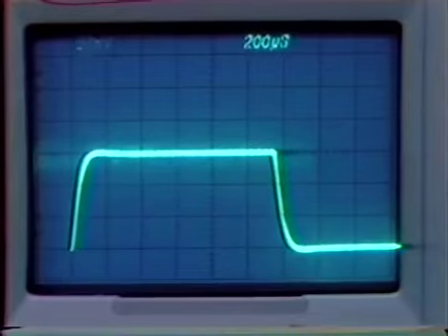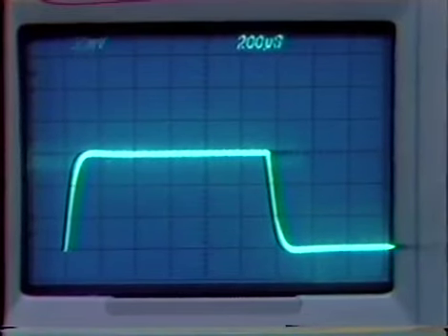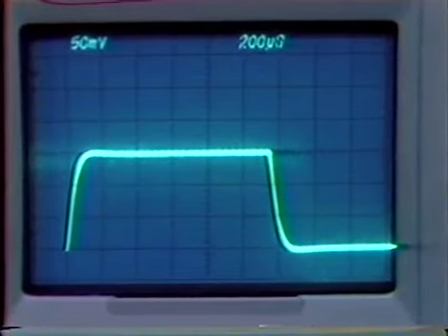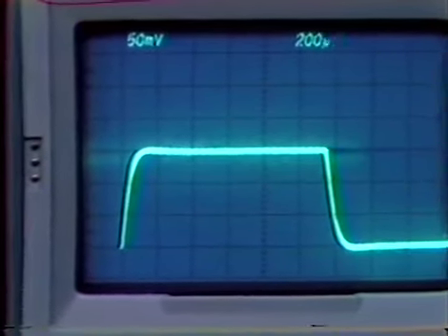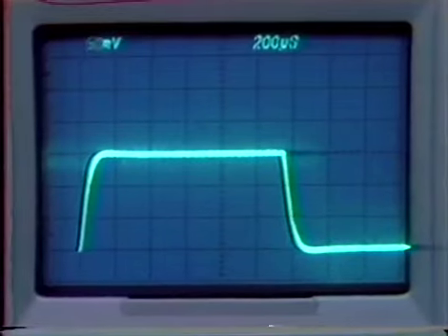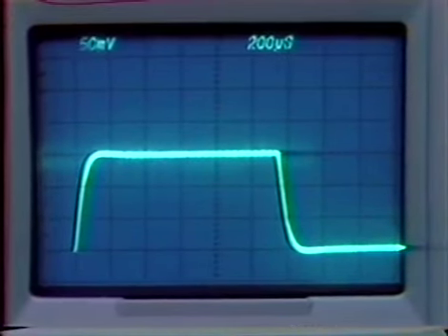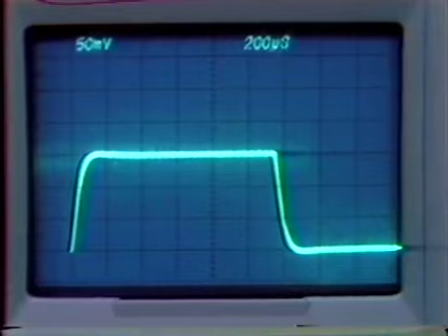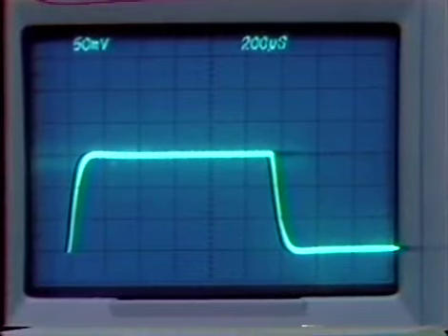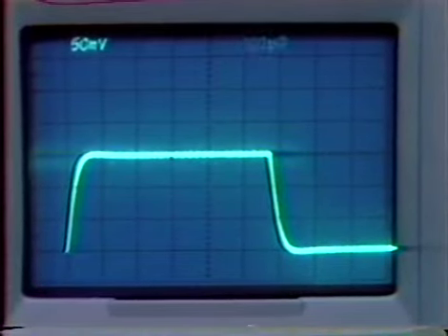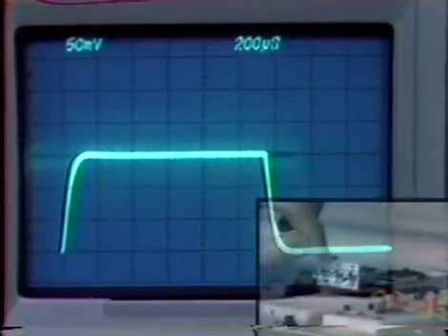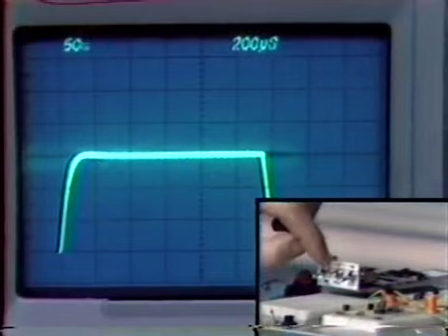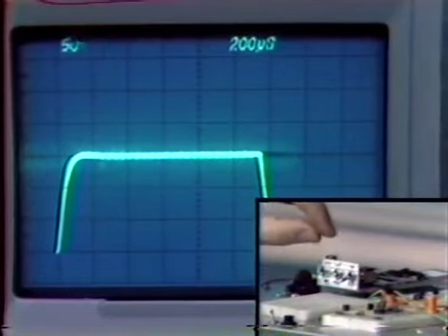That's not surprising. The phase of this network, this very simple approximation to a 1 over radical S network, changes far more violently as a function of frequency than does the 1 over radical S approximation using the much better ladder with a considerably larger number of rungs. So it's not surprising that relative stability is more dependent on the exact location of the additional pole.